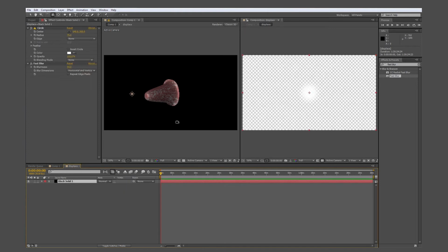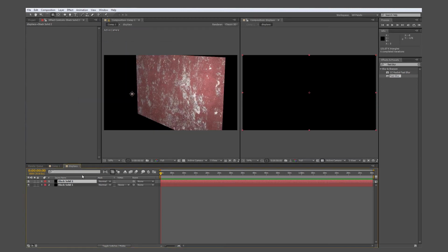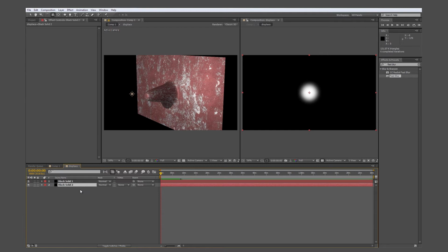If, however, you wanted to create the effect of, say, something coming through a wall or pushing through a sheet, then it would be a good idea to have luminance values here, even if they were just flat, without this cookie cutter type effect of the mesh. To do that, simply create a black solid and drag it under the circle, and there we have a white circle smoothing to a black background, reflected in the displacement here.